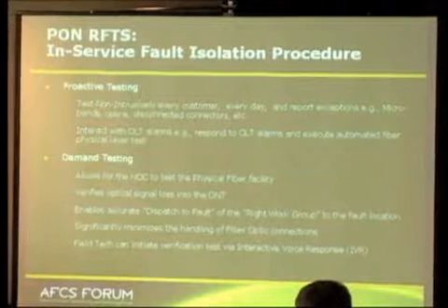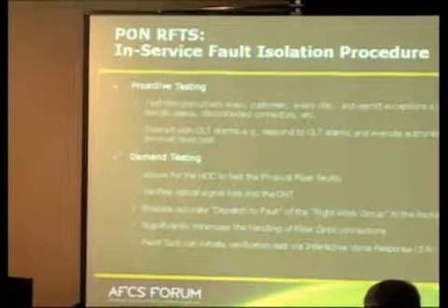And they're very beneficial. You don't obviously have the same issues as in the copper world. In the copper world, you've got corrosion issues, and it goes on and on, where you don't have that with fiber. But there are issues that occur. So we have proactive testing, and then we can see what's going on. Microbends, again, because we're using 1625, it's more sensitive, so we'll see a microbend that affects us before it might even affect the working wavelengths as such.